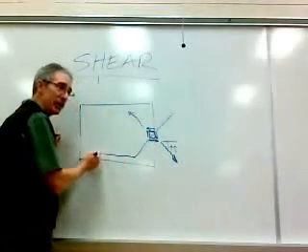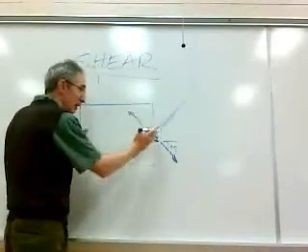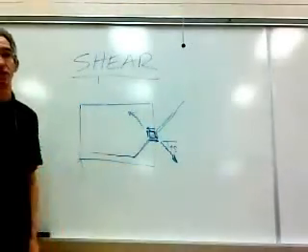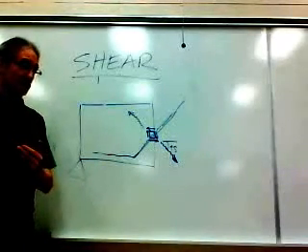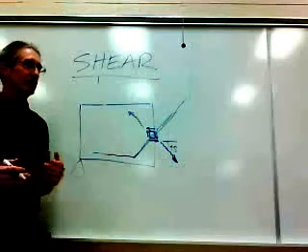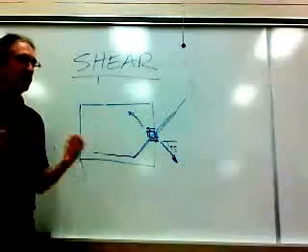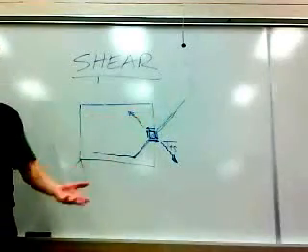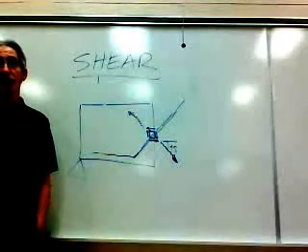It'll probably split the beam down here where the longitudinal steel is, and it'll run up to the top of the beam, and literally it'll break this chunk away from this chunk, and the beam will be ready to collapse. And it will occur in seconds, or maybe less than a second. That's what I always tell people: I've done a lot of inspection and consulting, going into old buildings, and I've seen one shear crack in my whole life in a real structure. Okay? Because most people that see shear cracks in beams are already on the ground.